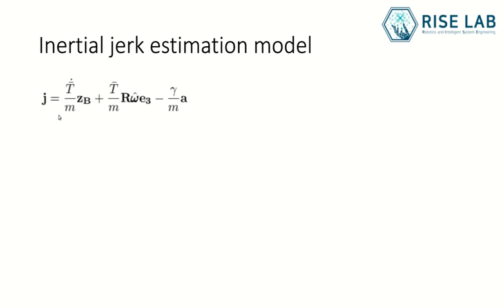So by doing this derivation, we arrive to this expression, in which by making tau equal to the augmented thrust divided by the mass, we arrive to this expression in which all terms are either the thrust, elements of the orientation, and values that can be obtained from the inertial measurement unit, IMU.